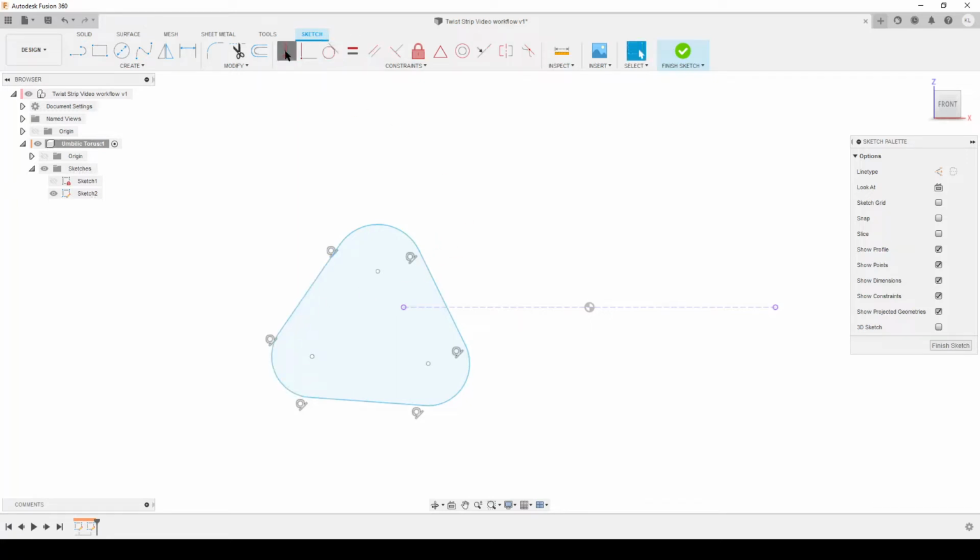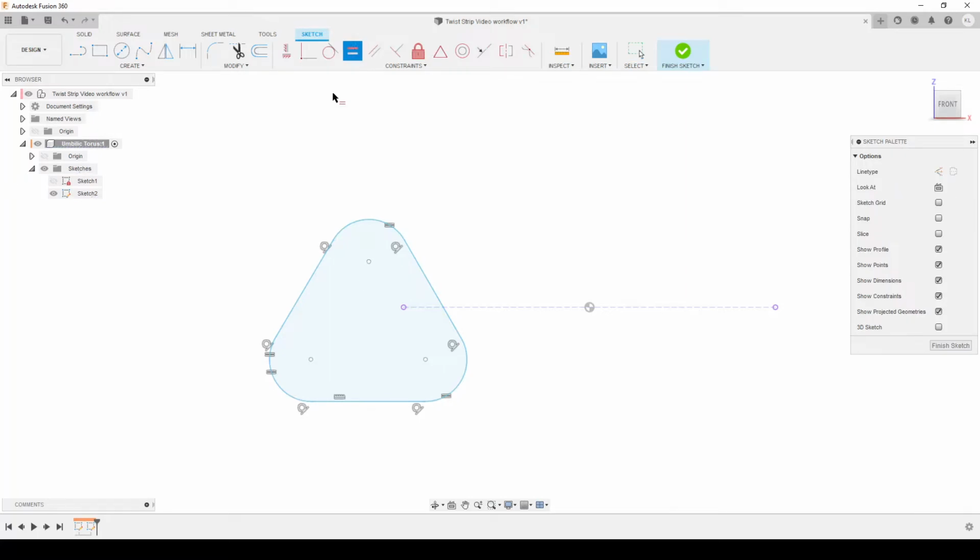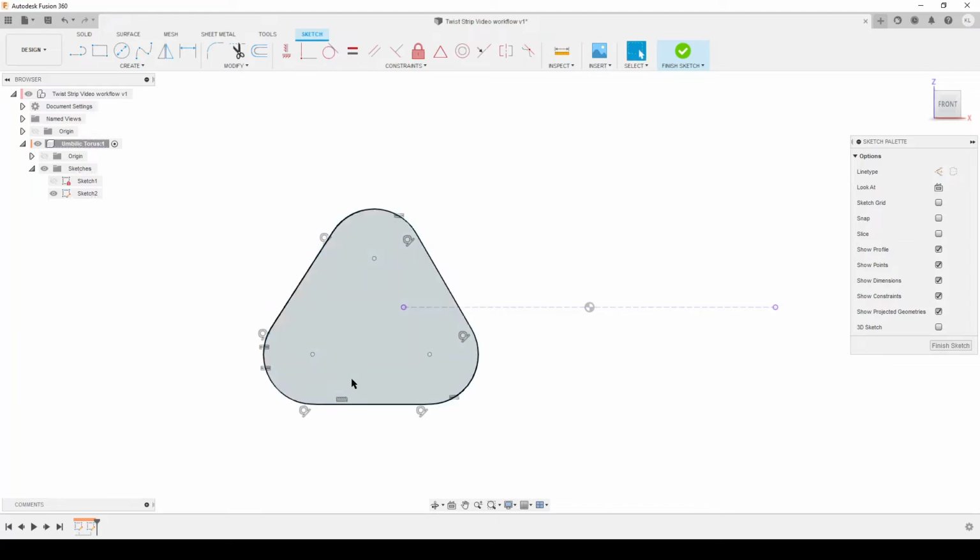I'm going to tell Fusion that this line is horizontal. I'm also going to tell Fusion that these three here are equal. Now, to turn off equal, you can see it starts moving around and stuff like that. So we're going to do lines from center. Also, I need to do construction lines. I want them; you can change it later. From midpoint to center point. From here, just find the midpoint. It's very good when I have a marker on the midpoint, which makes it a bit easier to find.